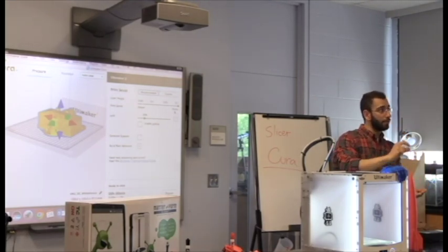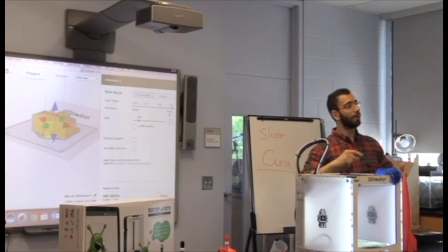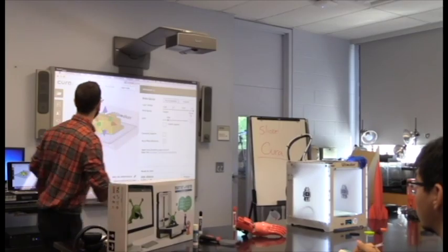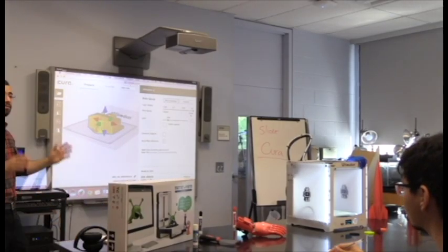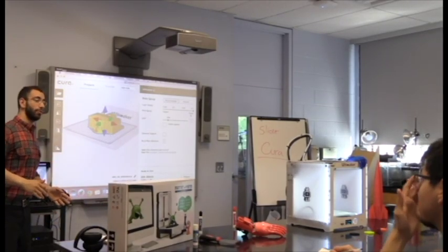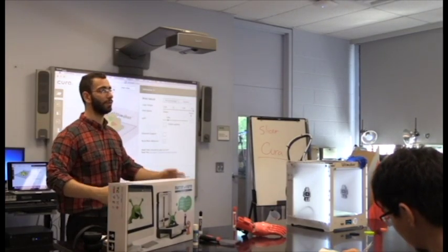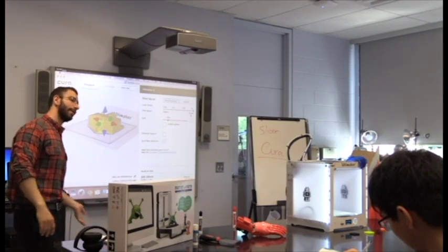But you see how, because the layer height is higher, it took fewer steps, which is why the print would be faster. All right, so layer height defines the quality of the 3D print. If you want high quality, you get a lower layer height. If you just want to test it, to see what it looks like and if it works, you put a higher layer height.